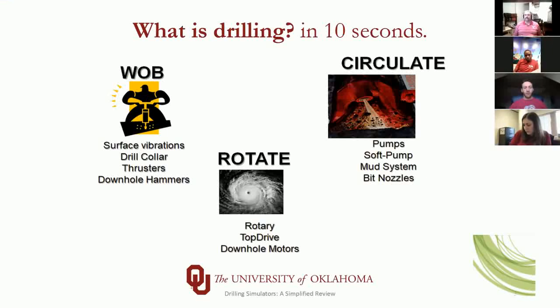We can use a top drive. Remember, since 1972, we are able to do that. But also today, we are rotating the bit by using downhole motors. And nevertheless, pumps, well, a pump is a pump, but the technology has evolved in creating pumps that are capable of running longer, with higher power, and we talk here about 6,000 horsepower for pumps. A lot of things have changed, but drilling still stays on rotate, circulate, weight on bit.